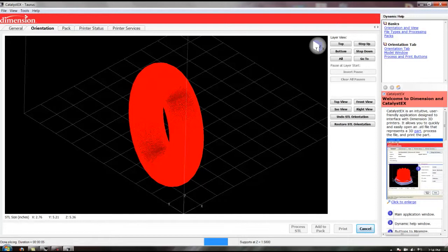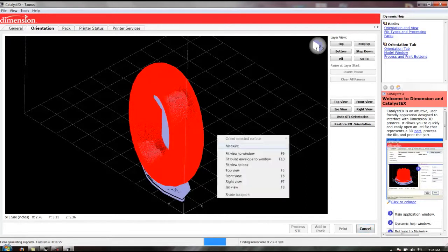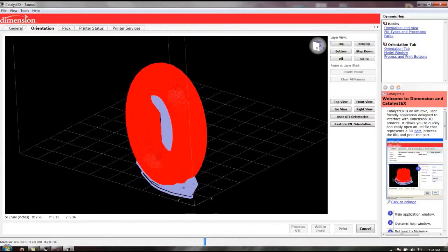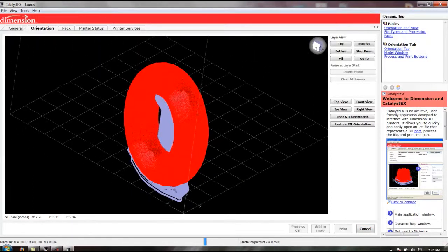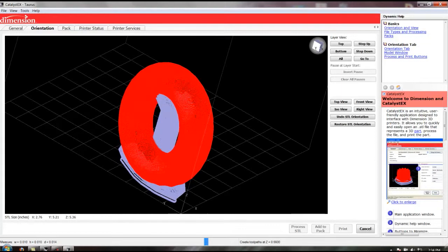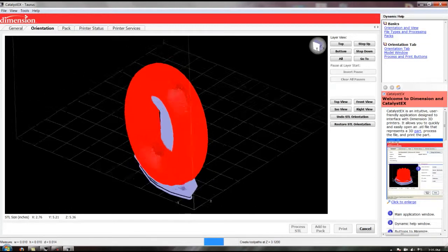The supports are necessary so that if there's any element that's hanging in midair relative to your model, it's got something actually solid to print on. The plastic that it prints is dissolvable, and you have to consider that whenever you're printing something with the machine, it needs to go through the acid bath at the end, and that takes time. As well, delicate models could possibly break in the turbulent acid in that bath because it is churning. But as we can see now, the lilac element that's appeared in our model, that's where it's building support.